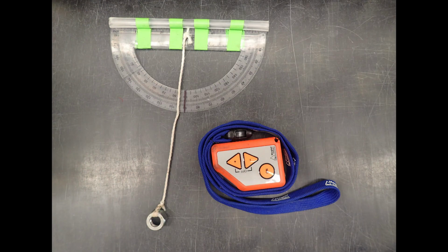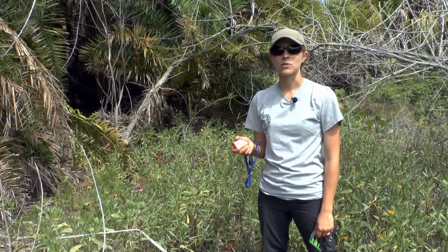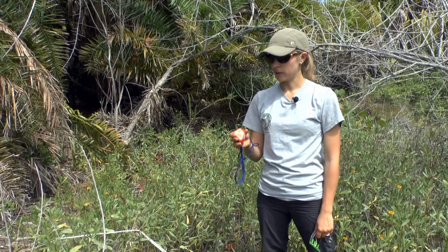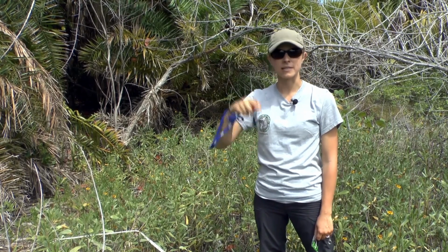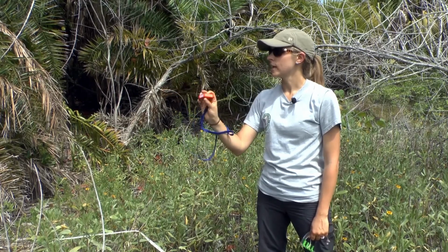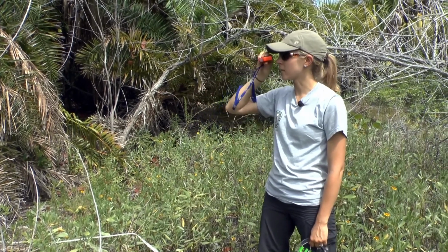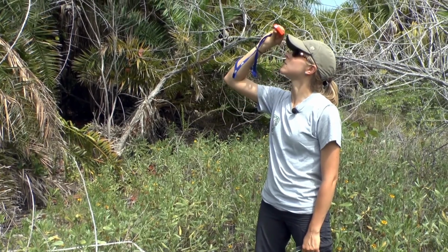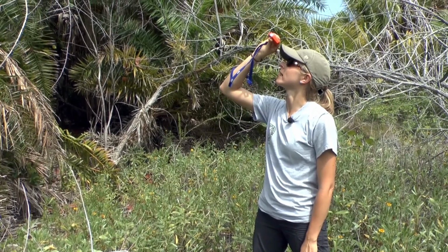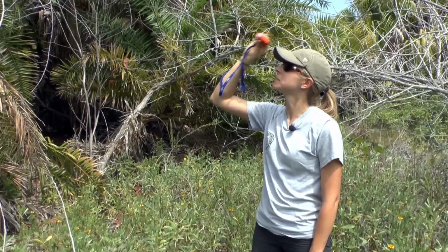There are various types of clinometers available that we can use to measure that visual angle to the top of the tree. To determine the height of the tree with a clinometer, you can purchase clinometers. So with this one, I need to input the distance that I'm standing from the base of the tree, and then I'll input the angle, the visual angle to the base of the tree, and then to the top of the tree, and the clinometer will calculate the tree height from that data.